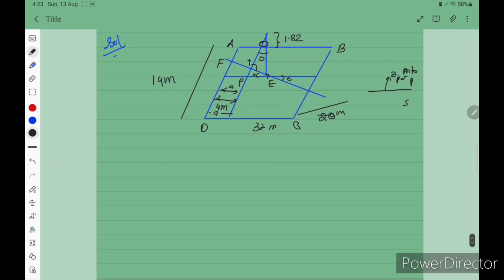Now let's solve. First is using the radar or sonic tape, no? So we use the first formula. Ullage corrected by tape, trim and list, because all three are covered, tape, trim, list, no? So we use the same formula.